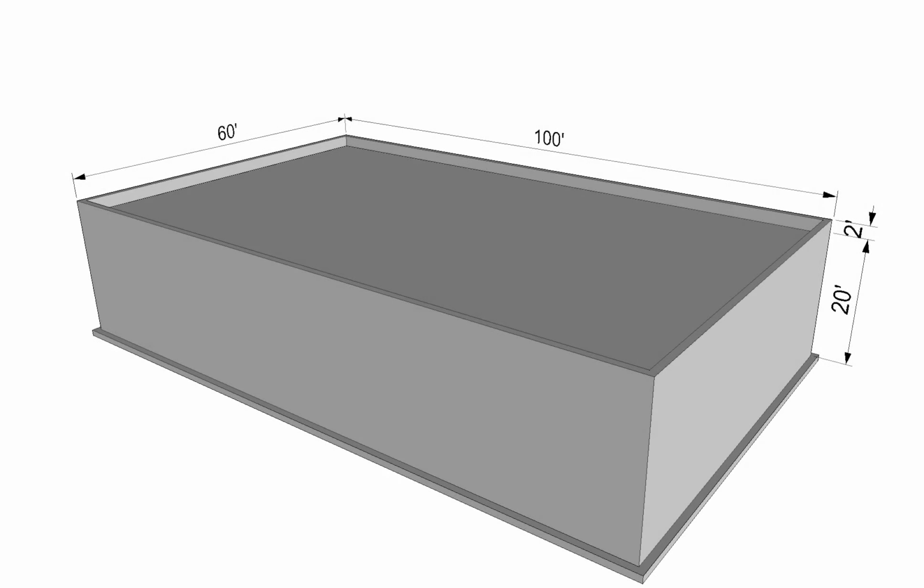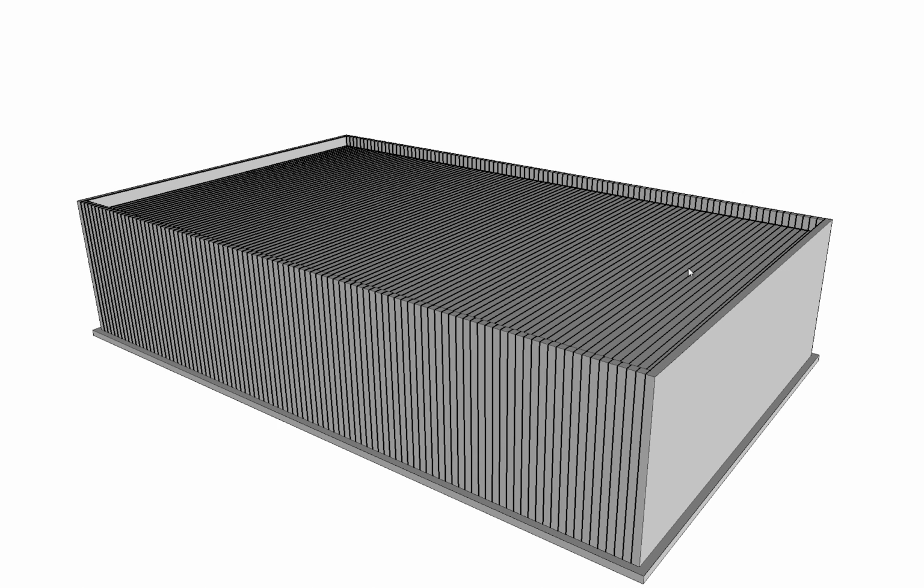So we'll look at a seismic load example here using this simple box building, 100 feet long by 60 feet wide. It's 20 feet from the foundation up to the roof level and then a 2 foot parapet on that. So to begin with, anytime we have a problem that involves lateral forces, we want to divide this into segments of 100 foot or 1 foot wide strips. So I've divided this up into chunks like this, and we analyze just one of those.